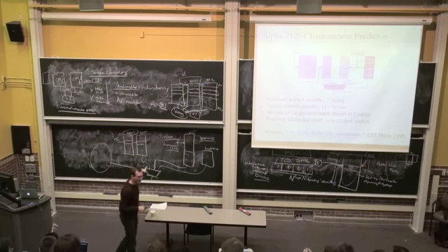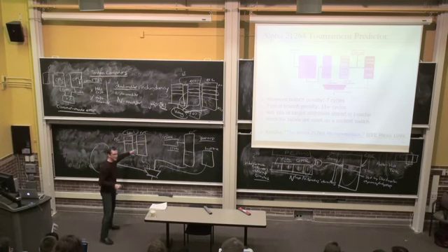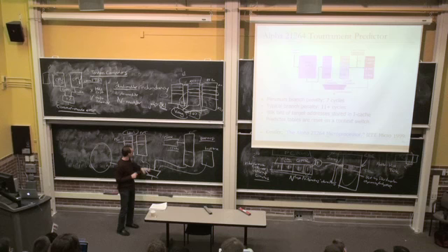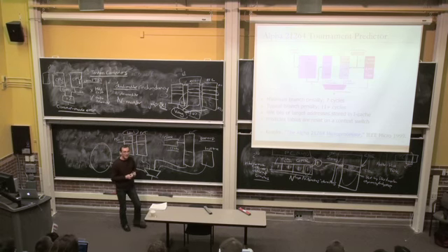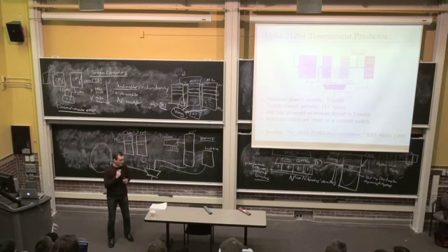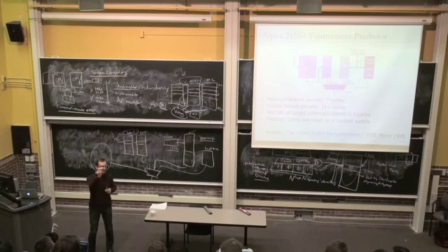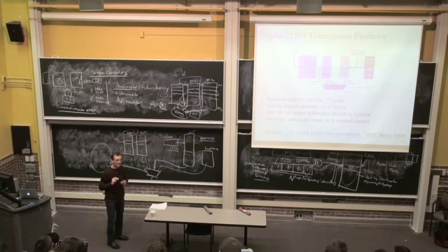It's an art. It is true. It's not clear exactly how you design it, but you can use many different pieces of information, right? For example, you can come up with something else to index the predictor. What can you think of? For example, your call stack depth. That could affect your predictability, right? Where are you in your call stack? What function calls you've executed? Instead of just taken or not taken.